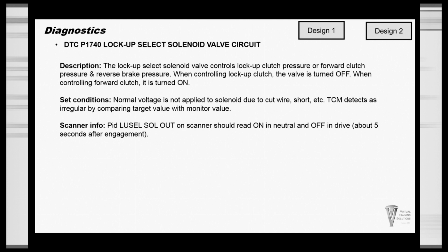The TCM is looking at a target value and a monitor value. So the PID information we'd be looking at would be the Lockup Select Solenoid out. On the scanner it should read on in neutral and off in drive, about 5 seconds after the engagement.